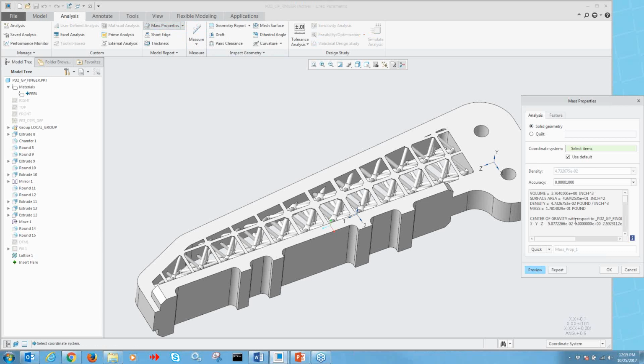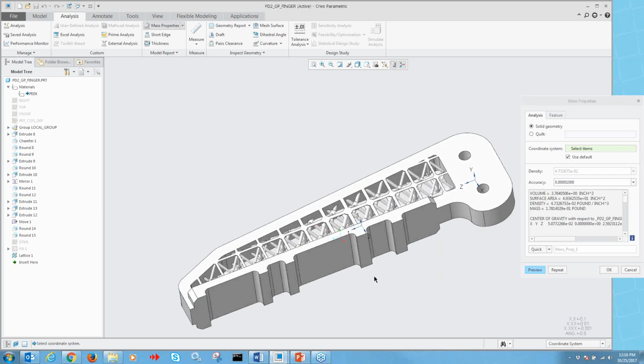We're down to 0.178. And originally, when we first started off, I told you we were at 0.265 to begin the process. So we've reduced that quite a bit on the size of that part. And again, we've conformed to the rigidity and made the part a lot lighter in the process with this material selection and then the lattice structures that we put in place. All right, so great. We've got the part all analyzed, optimized, ready to go. We just need to get it off to the 3D printer. So let's show you the next portion of the demonstration.